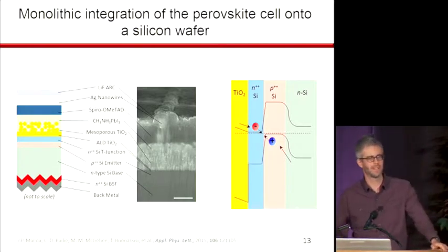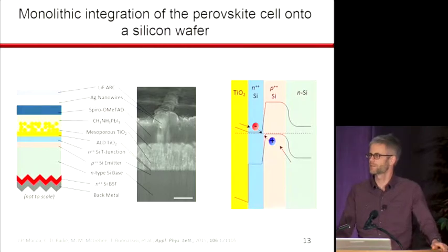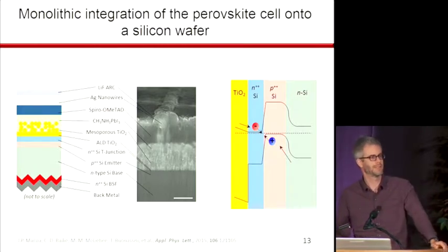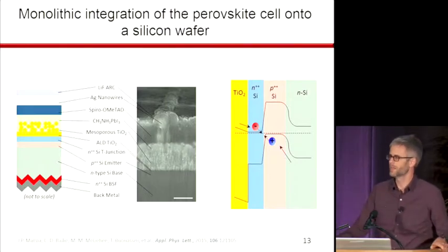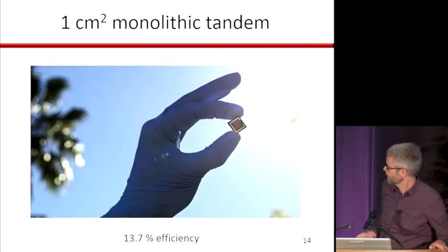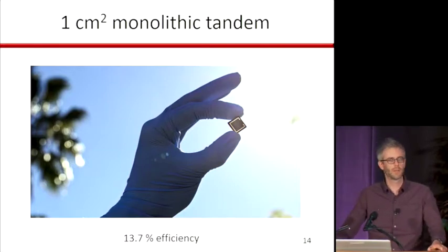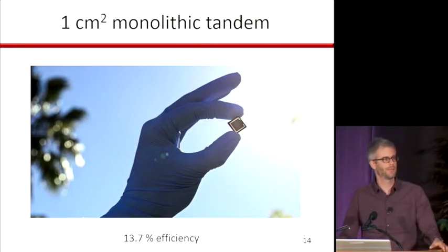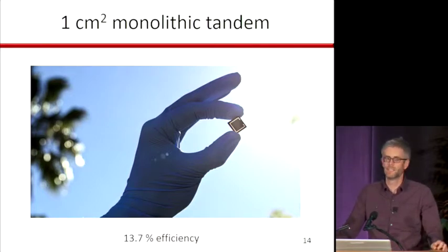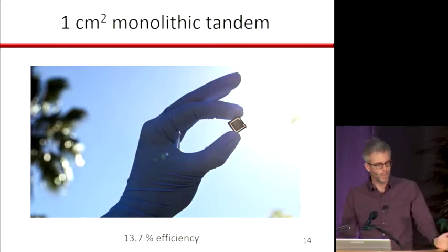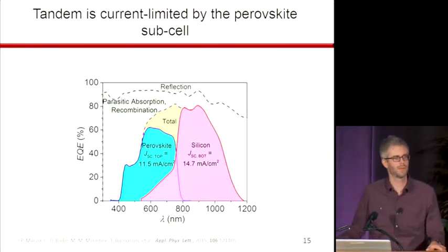And in research, some things take years to work and other things work the first time. This was one of those things that just worked perfectly the first time, exactly the way it was supposed to. We were able to move on to building the top layers. This is a picture of the solar cell, and it's a 1x1 square centimeter device. Our series resistance is low enough on our silver nanowire transparent electrode that we can make a pretty decent sized device with no metal grid lines running through the center of it. We only have about 13.7% efficiency right now.